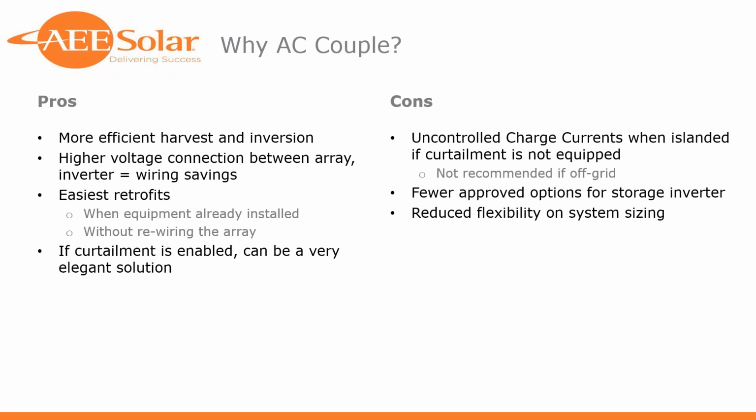And I'll say here, reduced flexibility on system sizing. We'll get into that as well. But what you see from a lot of manufacturers of battery inverters who do support this application is they support it with a particular set of circumstances on, call it, matching the ratings of the PV inverter to the battery inverter.